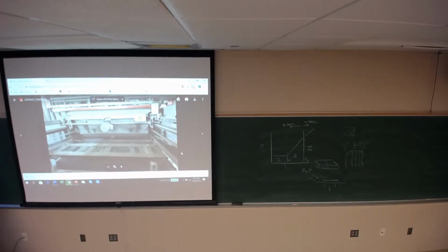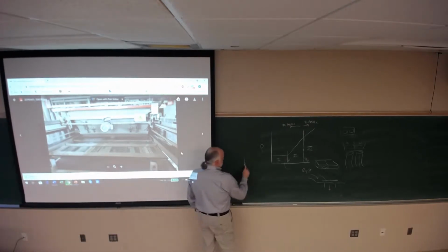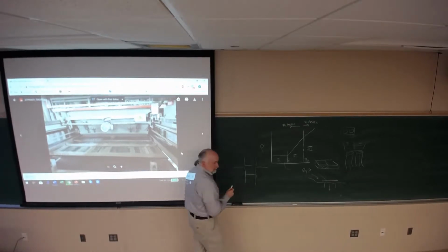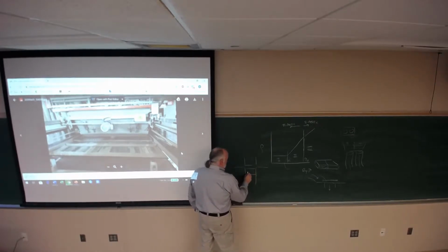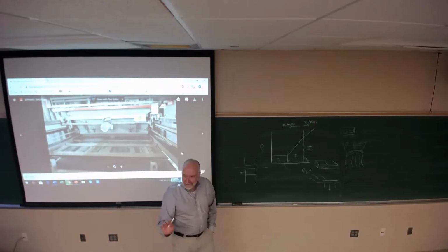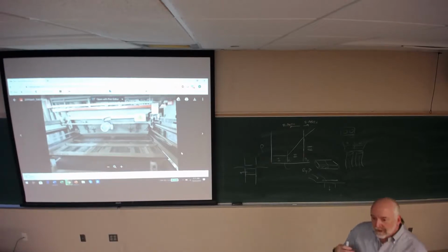All right? And what's going on? What's going on is there is no movement. When you press something, okay, like this, right? If you press in a die, okay, like this, we teach you about die wall friction, and you get this going on, you get your compact. There's no movement laterally. None. And I mean, like none, like at all. We get die wall friction.